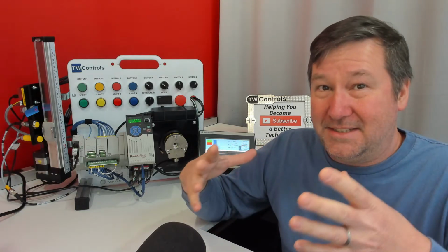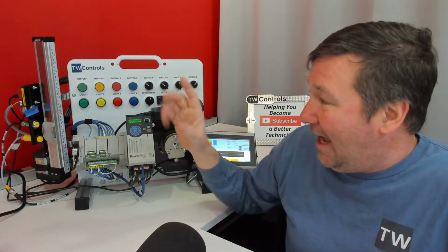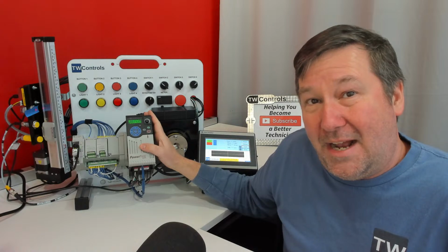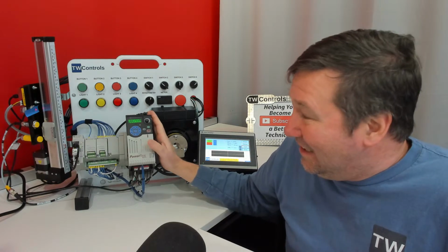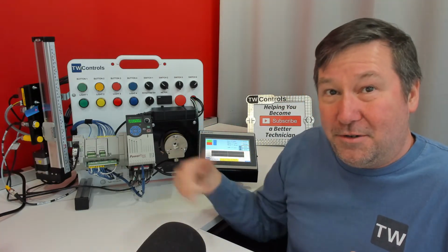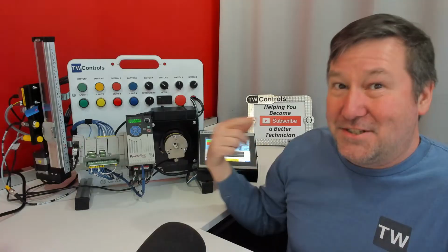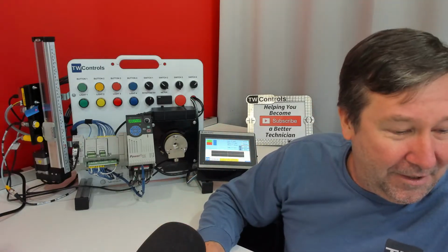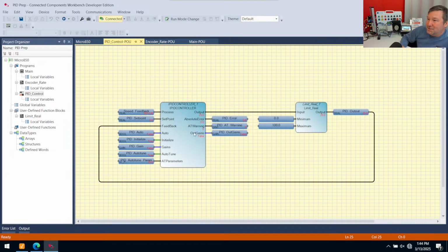And then a very important part, because you can get really caught up in the weeds of the numbers, is be listening, because after that, it's going to set your drive commanded speed back to 0. I talk to people in our class all the time. If you're applying 0 speed to a motor, it is still putting some voltage on that motor winding. And a fan cools itself by rotating. So you listen, make sure that you're not running this. But all right, so we're going to do it. We should see it go to a 1 here, and then hopefully shortly after a 2.